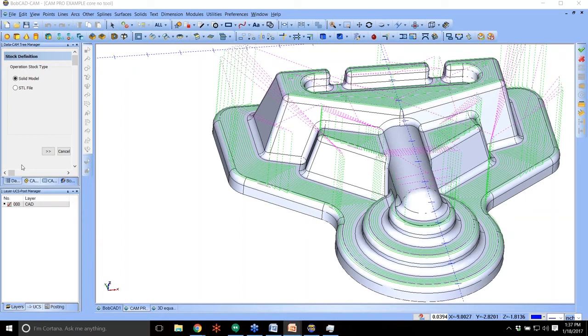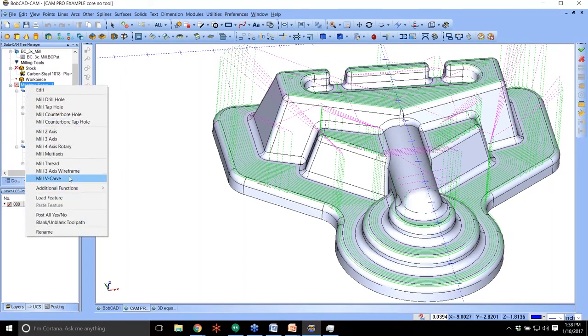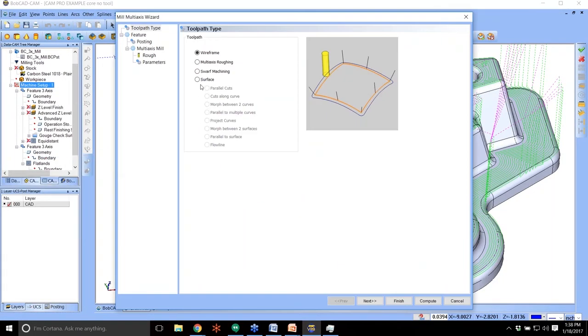Now this is a little bit further into the advanced options, okay? So you have an option for toolpathing that is in our advanced multi-axis. Now when I say multi-axis, it is called multi-axis, but that doesn't necessarily mean they're only for 4 or 5 axis. These toolpaths are used for 3, and they are what we call our advanced surfacing options.